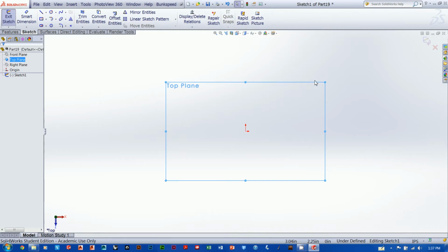This concept of looking at something normal to, or looking directly at it, is really important in SolidWorks, so pay attention to that. You can tell that we have now activated this sketch on this plane because if you look up here in the right hand corner, we've got these two little buttons, which are your exit sketch buttons. Just seeing those shows us that we're now inside of a sketch. So that's good to notice. Let's go ahead and make some drawings here.